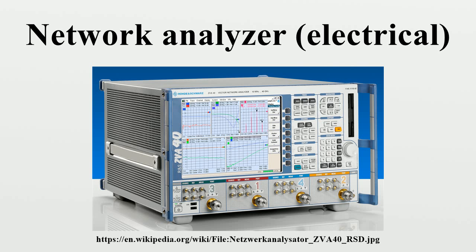This position is appropriate for measuring in calibration or error correction. A network analyzer, like most electronic instruments, requires periodic calibration. Typically this is performed once per year and is performed by the manufacturer or by a third party in a calibration laboratory. When the instrument is calibrated, it will usually have a sticker fixed to the outside, stating the date it was calibrated and when the next calibration is due. A calibration certificate will be issued.